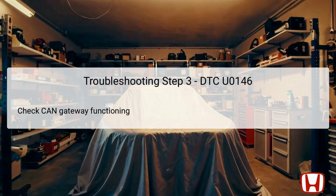In the third troubleshooting step, it's essential to evaluate the functioning of the CAN gateway, which serves as the communication hub for all control modules. This process involves checking for internal failures that may be causing the TCM to receive faulty or no data at all. Technicians should inspect the CAN gateway for any visible damage as well as electronic malfunctions that might impede its operations. Consulting the vehicle's service manual can guide further diagnostic processes and tests specific to the CAN gateway's functioning.